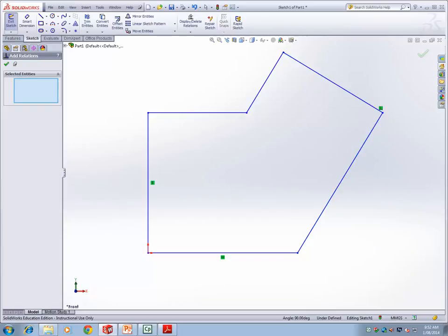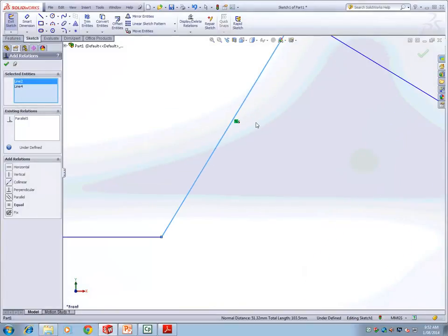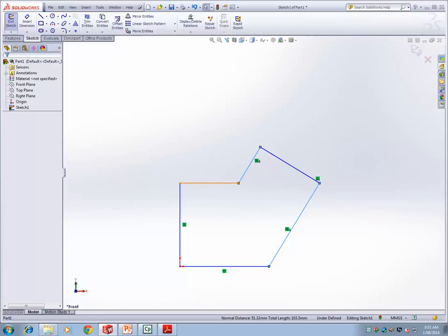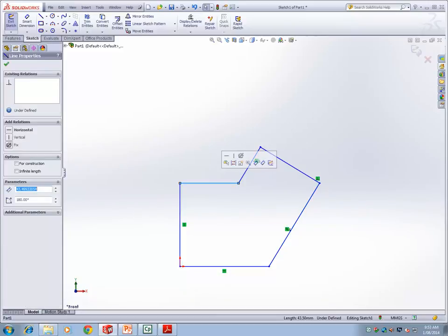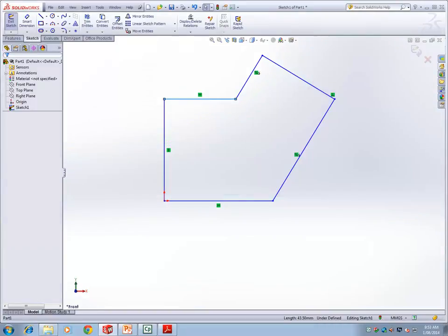Relationships are numbered. You must understand the numberings as well. They are numbered, and they are coming with a sign here, which is saying a parallel symbol. This is a perpendicularity symbol. Okay. Then I want this line to be horizontal. Okay, so I can make this one horizontal here. Done. Okay. Still my sketch is underdefined. Okay. What it needs is the dimensions on that particular sketch.